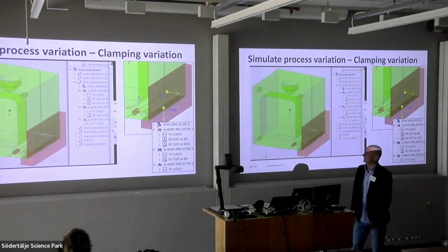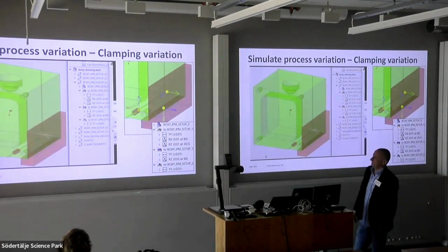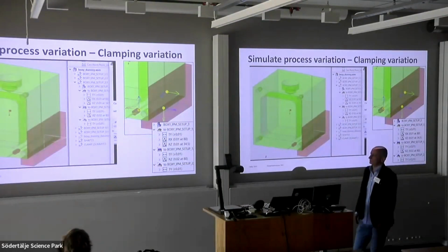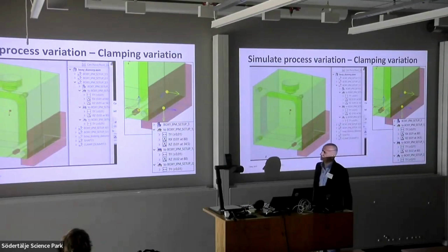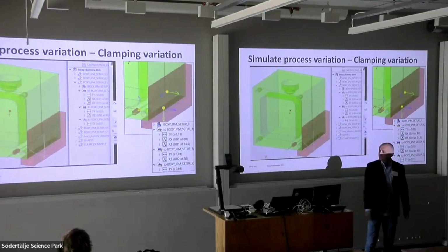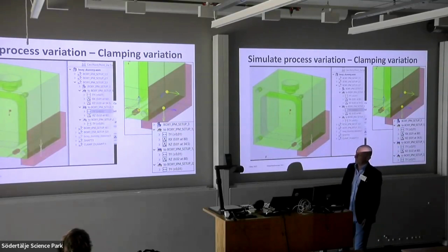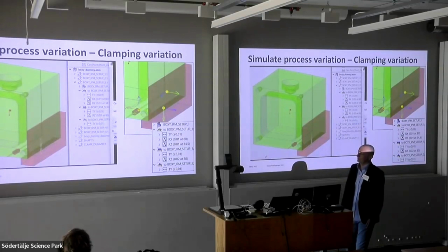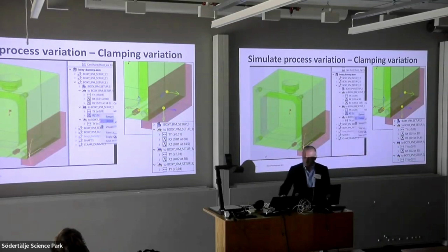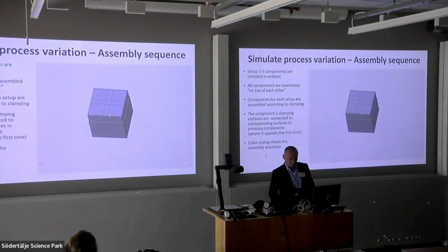So the biggest vertical surface can move in translational direction. We can also capture rotational degrees of freedom. So this is rotation of the long edge. We will of course capture also the other rotation, and you can graphically see that the short edge gives you more variation. This is more sensitive. Then we have the bottom surface, also translation and rotation captured, and finally a point constraint to fasten the detail in the side direction. So this was modeling of the clamping processes.